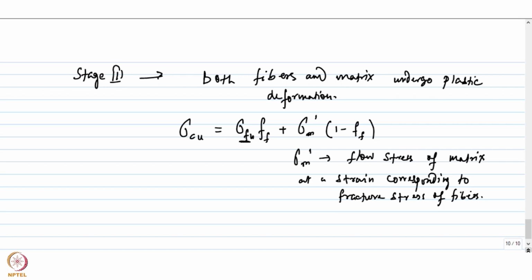Right? So in order to obtain any benefit with regard to the strengthening that the fibers could impart, there has to be a critical volume fraction of fibers beyond which the strengthening effect can be obtained. Okay, if it is below that critical volume fraction, below that critical amount, then you may not get the strengthening from the fibers.